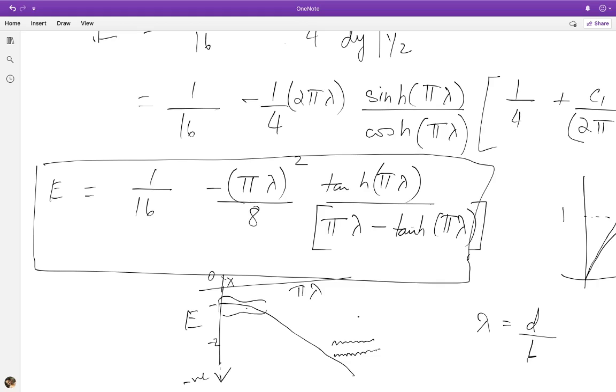So I've kept the pressure drop across the channel the same, right? That is the value of constant G. The perturbed pressure simply adjusts to the waviness of the wall to drive the circulations. So in a sense, if I do an overall momentum or overall energy balance on the problem, the input force I'm giving the problem, or consequently the input energy I give the problem, is the same, right? It's governed by the applied pressure gradient.